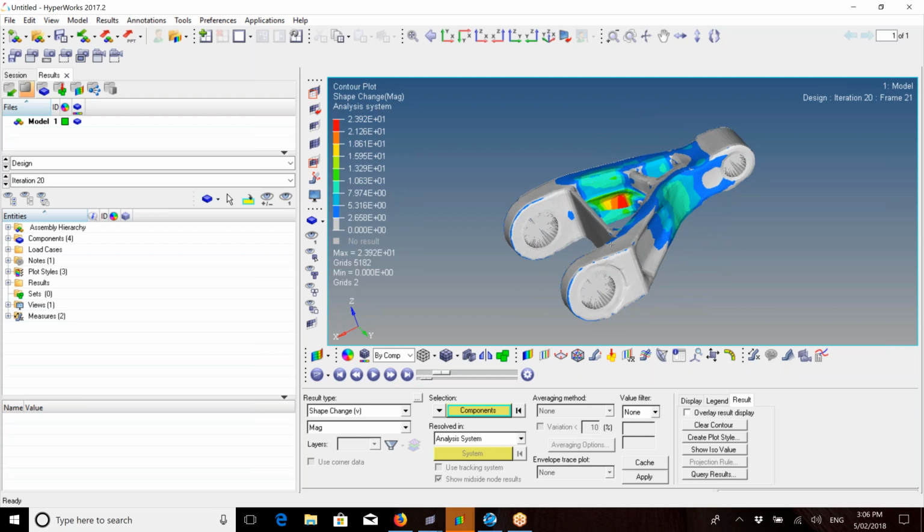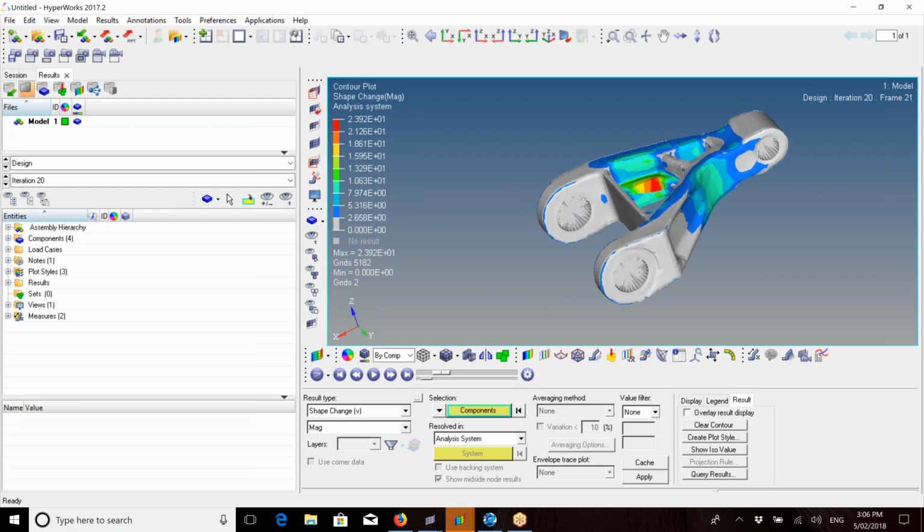So in those FSAE cars, maybe fatigue life isn't one that you need to think about as much because you're only doing a few short runs, but definitely the frequency where you could quickly see a fast failure in a part is one area that I would recommend looking into with these kinds of sections.